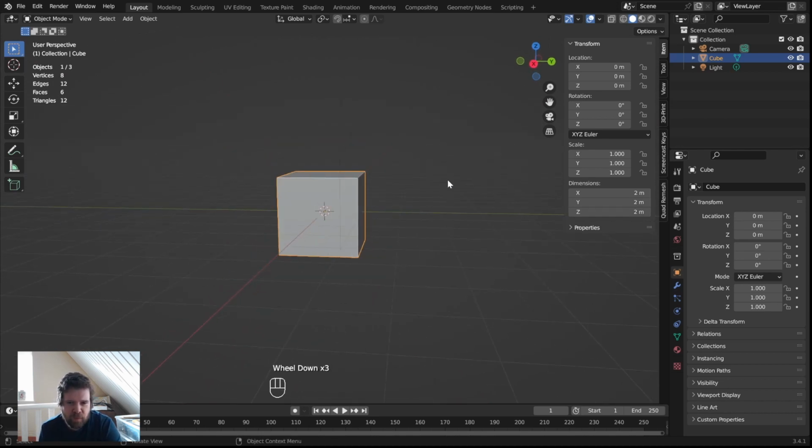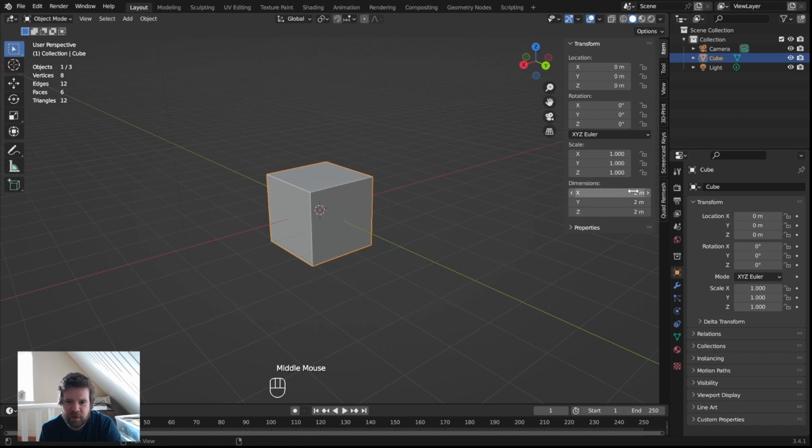But when we export this model for 3D printing, each meter will be 1 unit in the STL file that we most often choose to export as, and that unit, when imported into the slicer to prepare your file for 3D printing, is interpreted as 1 millimeter.